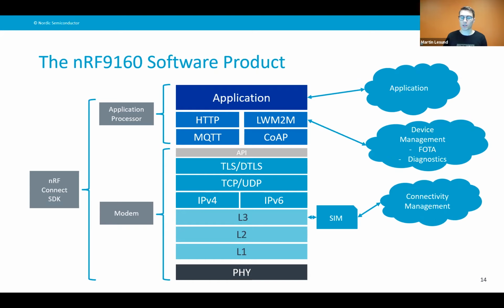Also the SIM card talks directly to the modem. For the application processor, we also have the NCS that has support for HTTP, LWM2M, MQTT, CoAP, and you run your application on this. You have support for device management, FOTA, that means firmware over the air updates. So you can update your application over the air, or maybe the modem firmware if you want to.